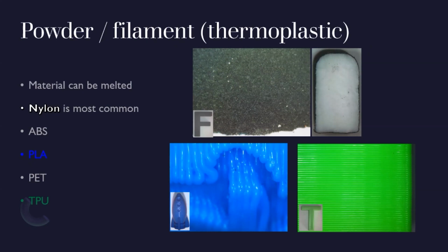However, one of the drawbacks of nylon is that it's hygroscopic, which can affect the quality of the final product and requires that the starting material be stored in a dry condition and also used dry. On the other hand, because it is hygroscopic, nylon can be dyed easily, which is what I actually found in the letter F object that came with our 3D printing kit.